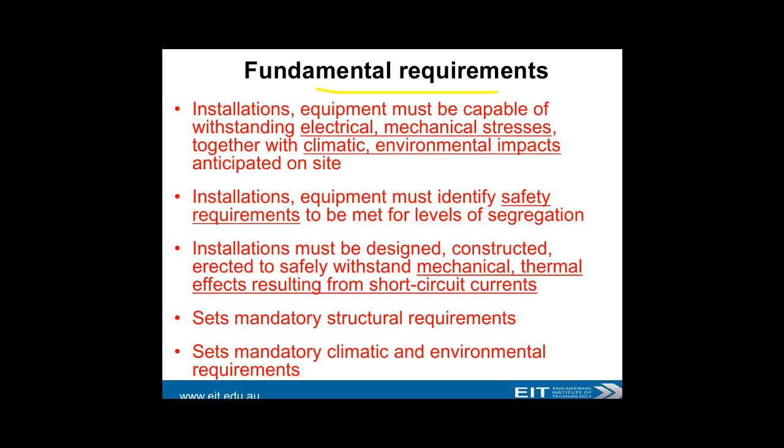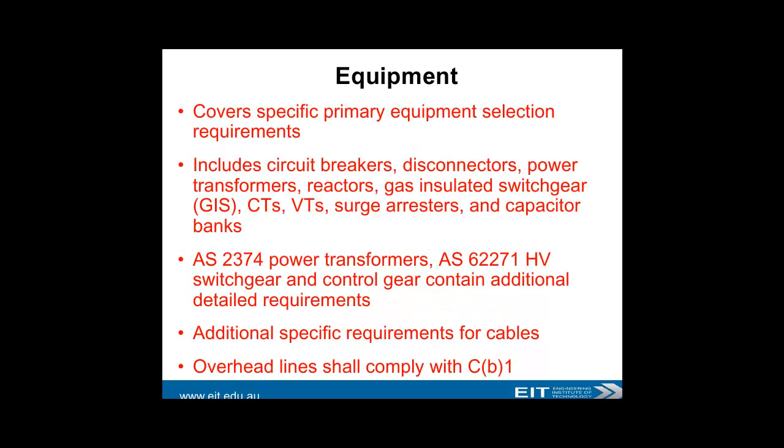Fundamental requirements, obviously: installations and equipment must be capable of withstanding electrical, mechanical, climatic and environmental impacts. Installation equipment must identify safety requirements, be designed and constructed to withstand mechanical and thermal effects from short circuits and electrical faults, and obviously structural requirements, and mandatory climatic and environmental requirements, really important.